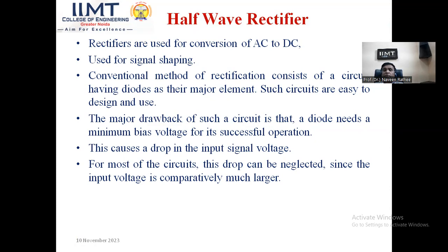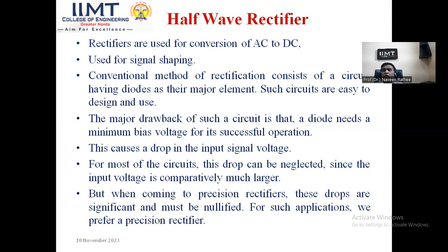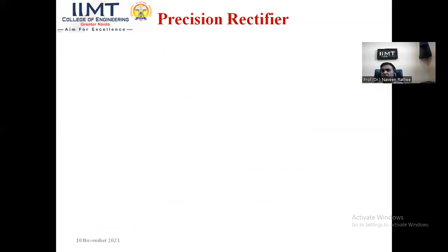But when we talk about the precision rectifier, these drops are very significant, because if these drops are present along with the input signal which is to be rectified, then first we need to nullify them. If these drops are not nullified, they can also be seen at the output. For such applications, we generally prefer a precision rectifier. So now let me go straight to the precision rectifier.